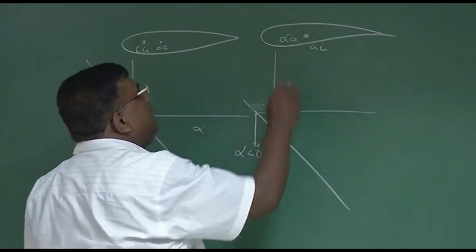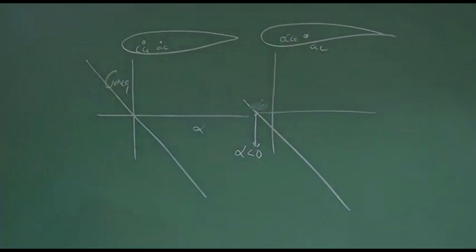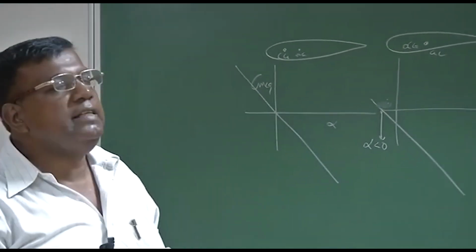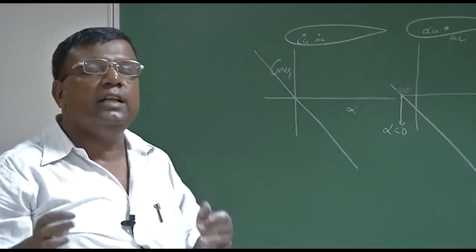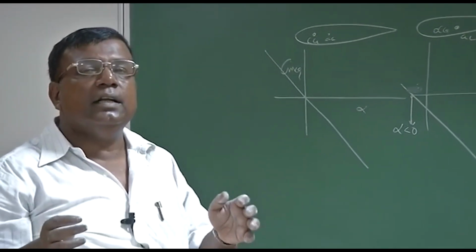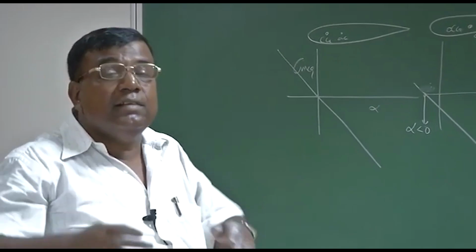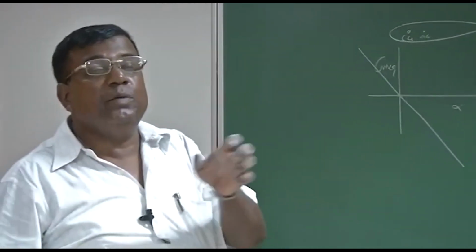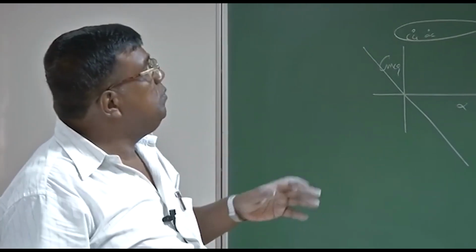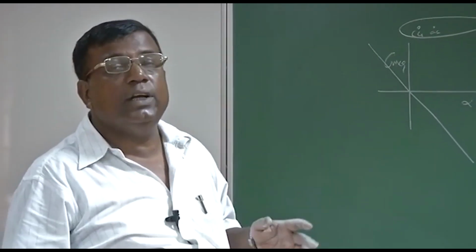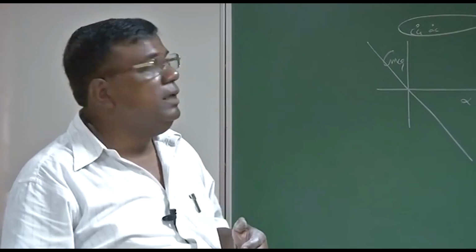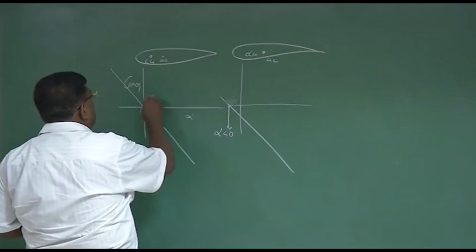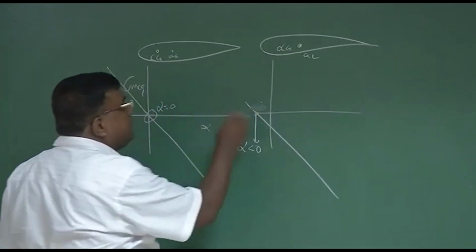That is, if I make a wing alone configuration, whether it is having a symmetric aerofoil or a cambered aerofoil, if I just put the AC behind the CG, that is, I do the mass distribution such that CG is ahead of AC. AC is governed by the planform, right? Nothing to do with the weight. But CG I can change by distributing the weight. So I distribute the weight in both the cases such a way CG is always ahead of our aerodynamic center. So they will be statically stable. But my problem is what? My problem is I don't get positive alpha in either case.